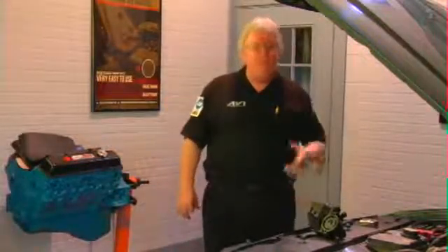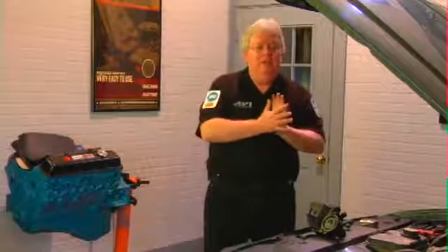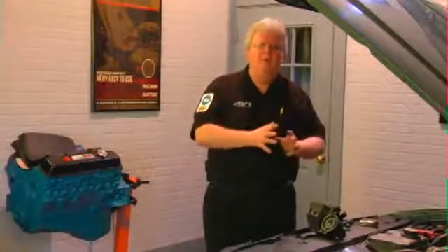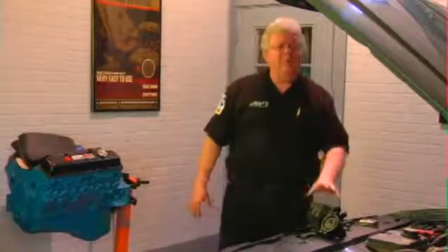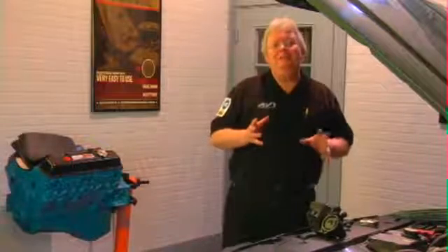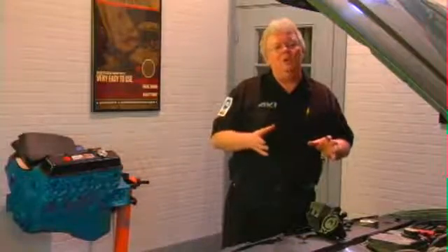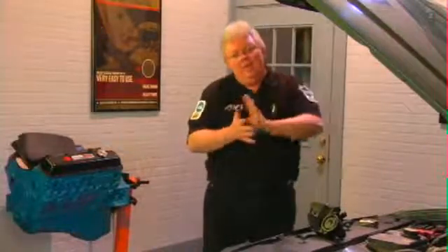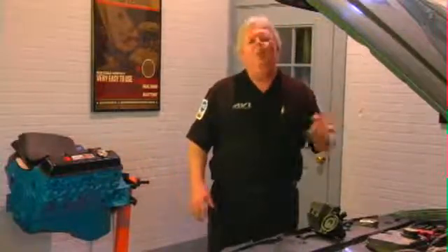The buzzing noise, what is it caused by? Well, it can be caused by vibration from the engine, specifically the power steering system. It has its vibrations of its own, grounding out against something. So a hose, or the pump itself, or the reservoir. There may even be a TSB, Technical Service Bulletin, addressing that vibration. So make sure you look and inspect all the lines and the hoses, even the cooler, the reservoir, and make sure we don't have something loose or something that's been bent and kind of vibrating against a piece of the body, inner fender well, firewall, whatever.